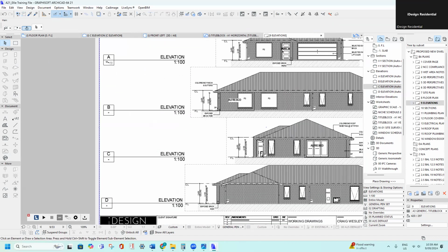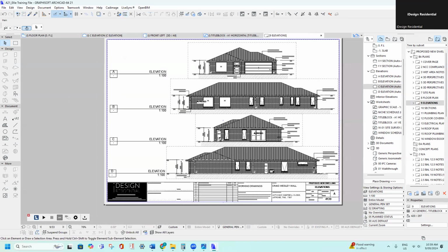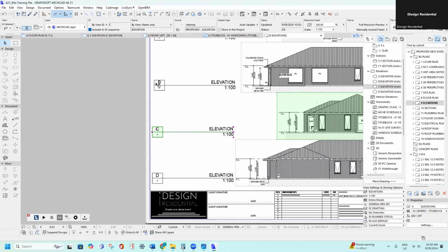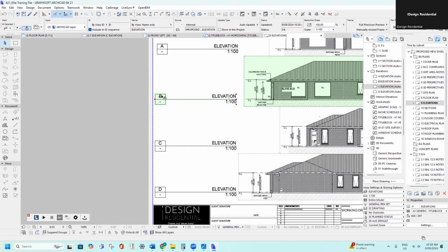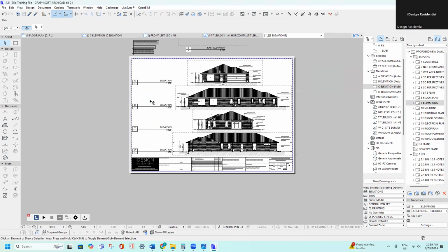And if you press M, you can see that all of these are in a straight line except that bottom one. And the reason why is because this bottom one, I've just moved it over. So you could click on each marker and press that button and hold shift to drag it left to right in a straight line and just drag it down in a straight line, hold shift. And then it makes sure they're all in a straight line. So it just looks more legible.